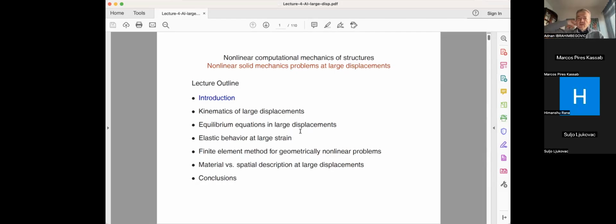If you go all the way to the end of chapter 4, that allows you to have a large elastic, large plastic deformation, and use what is called multiplicative decomposition of the deformation gradient into elastic and plastic parts, which reduces to multiplicative decomposition of your principal stretches. And then you take a logarithm, turning the logarithm of the elastic stretch into one deformation, the logarithm of the plastic stretch into another, and you get additive decomposition just like in the small deformation setting. So this is roughly what I wanted to talk about today.